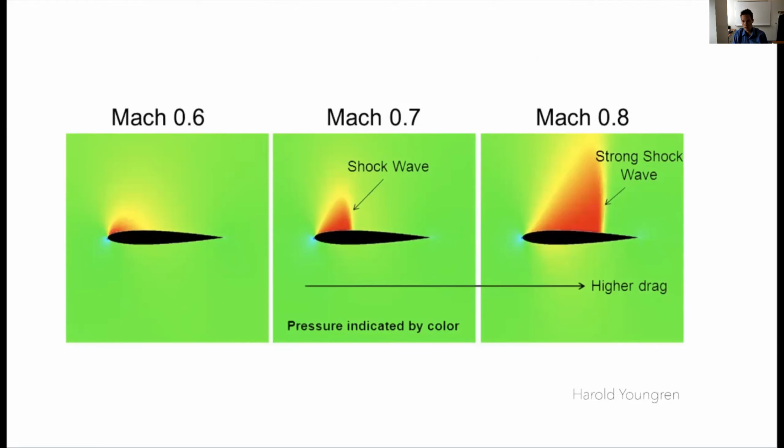This is going to be, like I said, kind of like a boundary layer. It's a high entropy, irreversible process, with lots of drag potentially associated with it. Okay, so it passes with a shock wave. If I'm going even faster, and these numbers are kind of typical, a transport aircraft that you fly in is going to be somewhere around Mach 0.8.